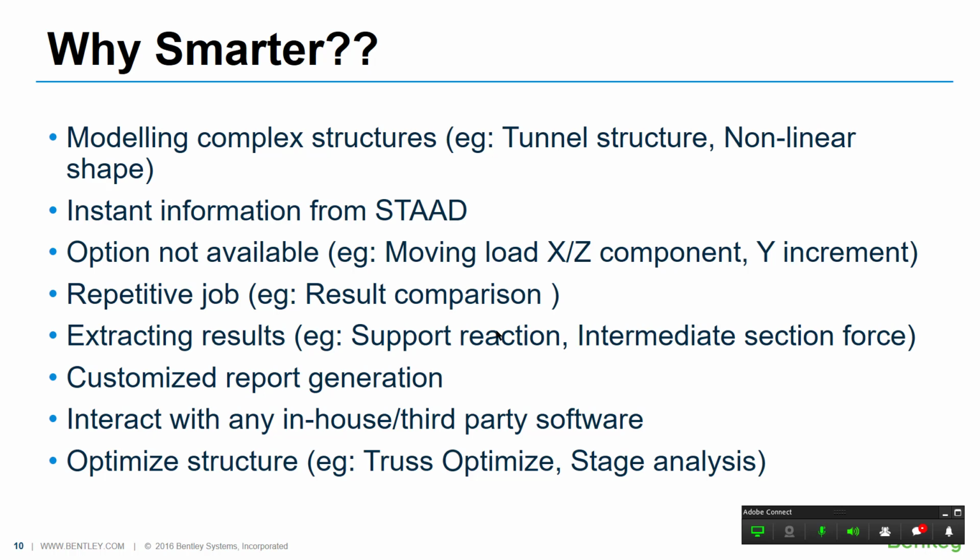You don't need to copy and paste the values from STAAD. You don't need to filter the values, what should be our highest maximum positive or negative bending moment value or the reaction value. You can just extract the values in your program, filter them, and design with the maximum value. So this is very easy. Using this particular option we can basically optimize the program that we have created, and we can readily transfer data with STAAD.Pro.